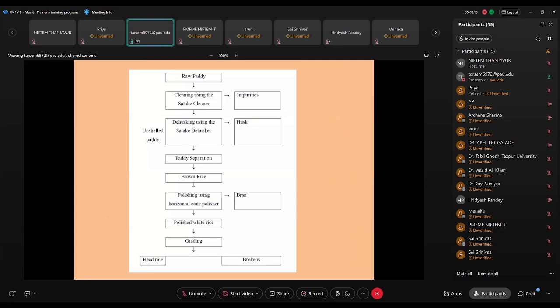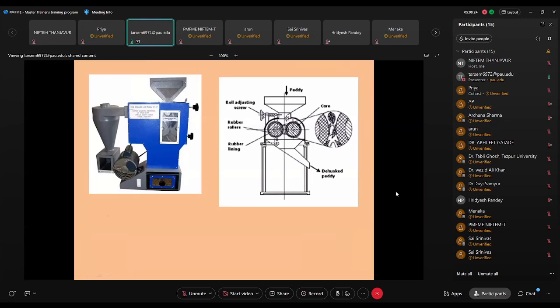If we are getting white rice, then we have to remove the bran. Even for getting the brown rice or commercial brown rice, 1 or 2% of bran may be removed. And the machines, like I'm showing a dehusker, a simple rubber roll dehusker we are using. In the modern rice mill system, we use the rubber roll dehuskers for removing the husk content, which is about 20%. These are laboratory models where we can assess the milling quality of basmati paddy, or even some other rice also.